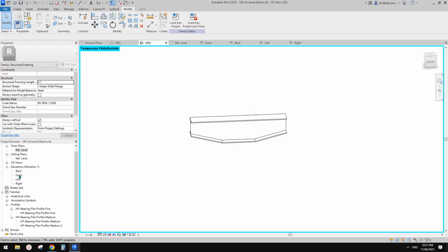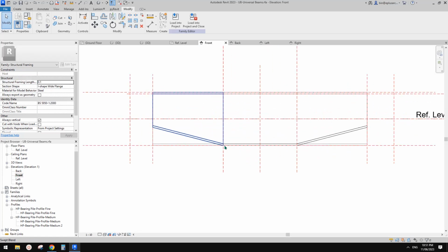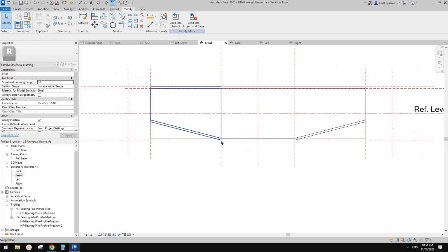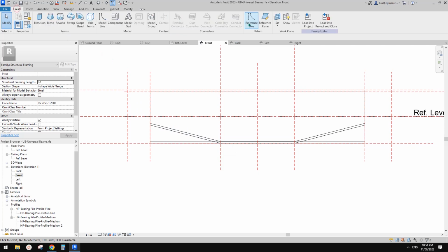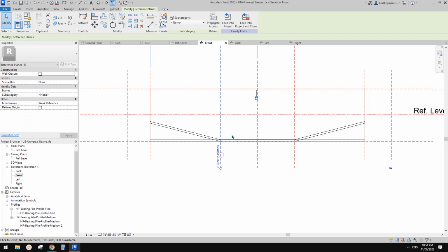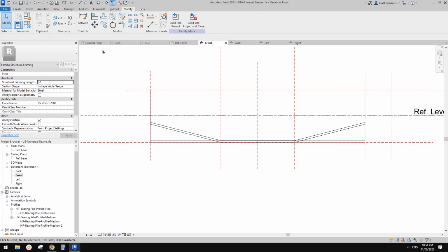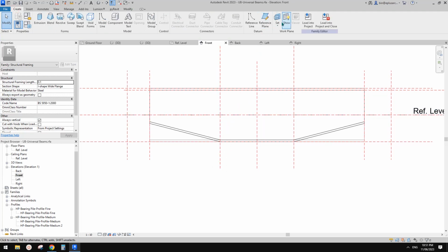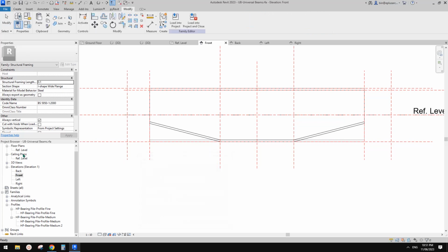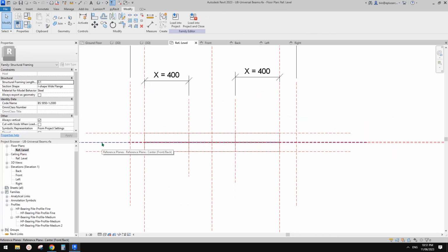So for example, we can just create one from this point and then create, yeah, I think we can just do some like a reference line, because this one needs to follow this reference plane, and with an angle, right? So what you can do is you can create a reference line, pick a plan. Maybe let's go to floor plan, so we can pick the center plan.